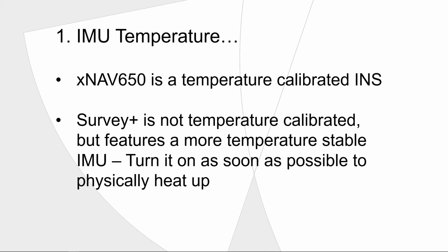It's small but not negligible. So if you want good data, I advise to turn it on as soon as possible to allow it to physically heat up. Any electrical device, when you turn it on, if you feel the computer that you're watching this on right now, I'm sure it will have a slight heat to it. That's essentially what we're trying to do, just heat it up to a normal working temperature.